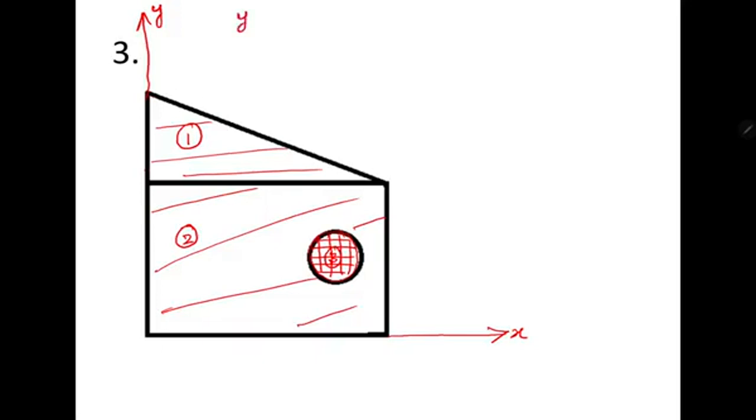So the formula will be y bar is equal to a1 y1 plus a2 y2 plus a3 y3 divided by a1 plus a2 plus a3. But here the third plane figure has to be removed, so you need to write that as minus. Here also this as minus. So now if I take y bar, the formula as it is